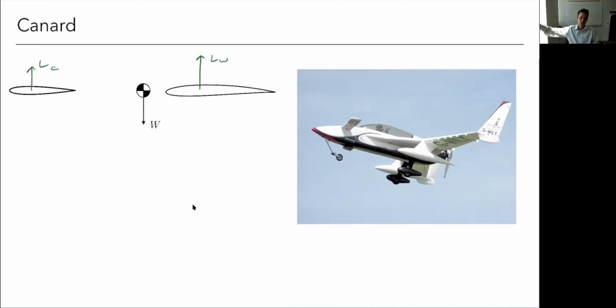So that's okay. But for the canard, if we move it too far forward, our aerodynamic center would come forward and be unstable. So it doesn't go that far, but that means to generate the moment that we need, it's going to be a pretty significant chunk of our total lift. What that means is that the wake from the canard is going to be fairly significant, and it's going to cause some interference on our wing.